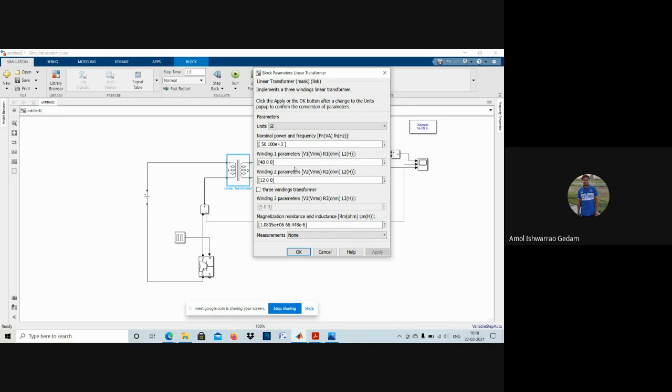If you go beyond 0.5 duty, we can go up to 0.6 also, but after 0.6 the voltage will go on decreasing in case of buck boost or boost also. So we will consider the standard condition as 0.5. So I have taken 12 volt at D is equal to 0.5, and the RM we will keep maximum 1